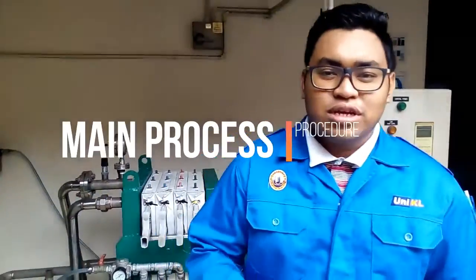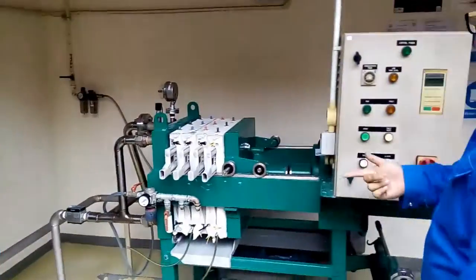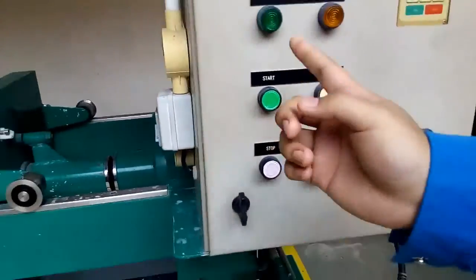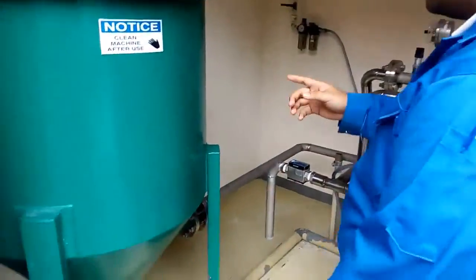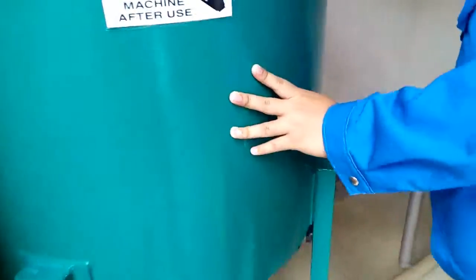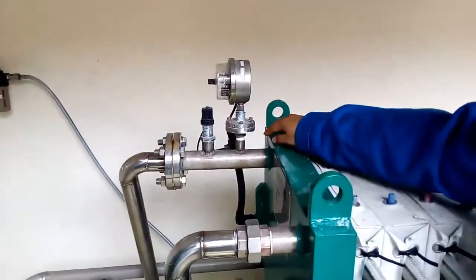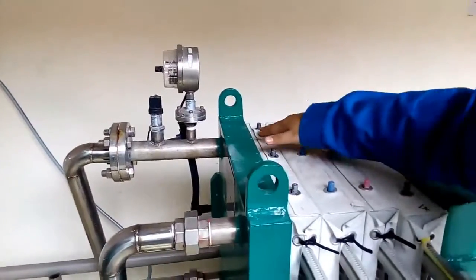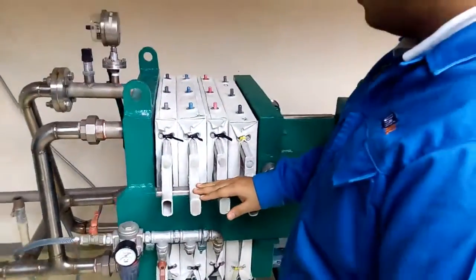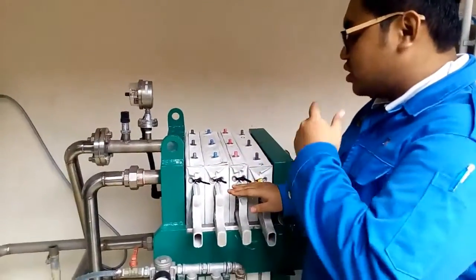Assalamualaikum. Right now I will continue Mr. Shafiq's procedure. After we push the start button, the pump will start. So the mixture from this slurry tank will flow into this pipeline, and then it will be transferred into this pipe. So it will go through the filter frame here. At this point, the solid liquid extraction process occurs.